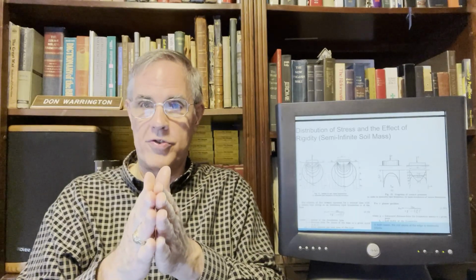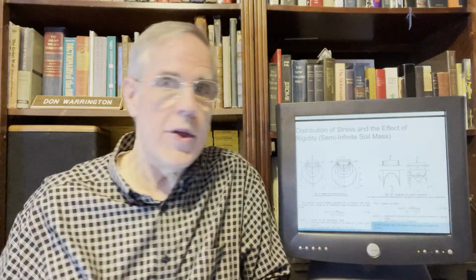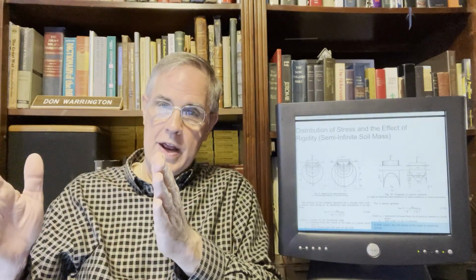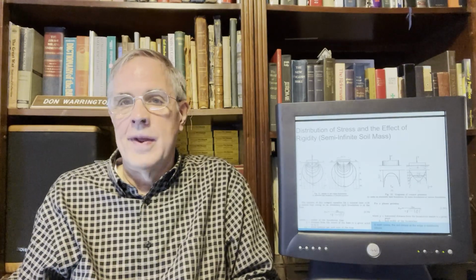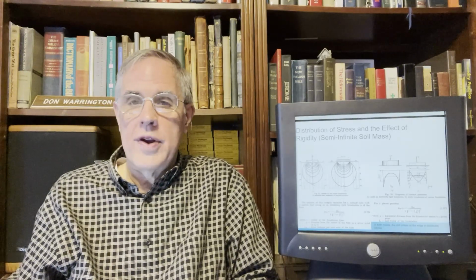And you will see that when, for example, rho, the distance of a point of interest from the center, and r, which is the radius, are the same, this thing blows up. And the same thing where y, the distance from the center, hits the edge, B1, the half distance from the middle to the outside, it also blows up. Now, that's elastic theory. In reality, what's going to happen is something along these lines.